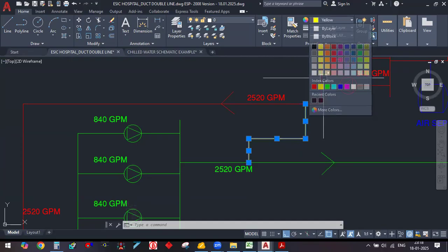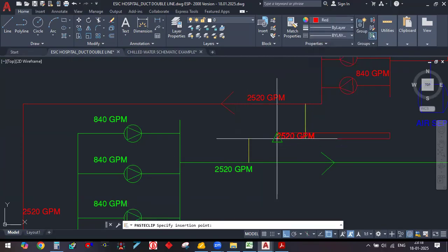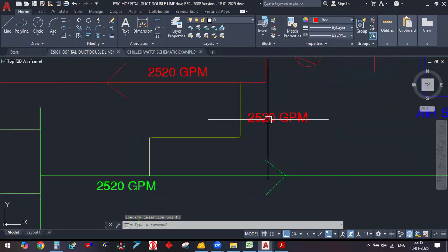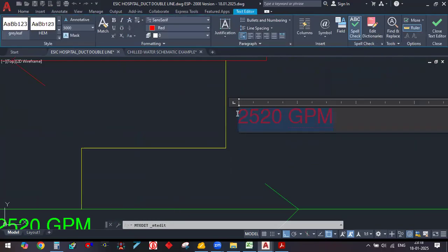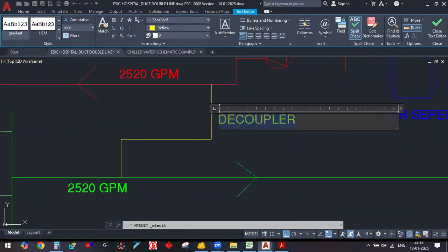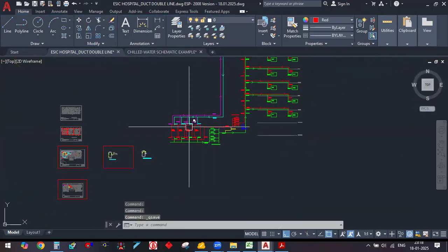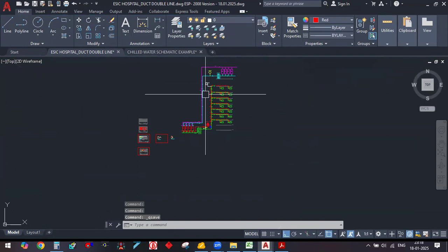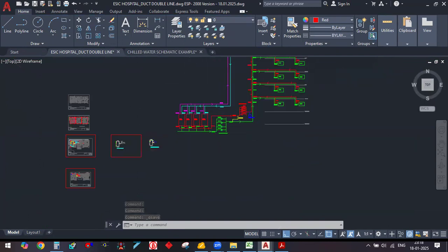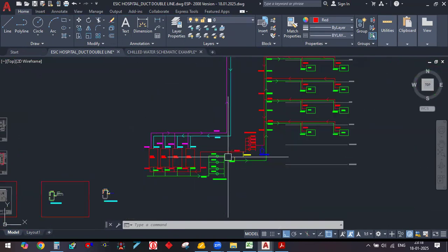Excuse me, sir. Now whatever we have done, this is the water cooled chiller. In the air cooled chiller, this cooling tower will not come. Yes, in the air cooled chiller, you just have to remove that. Rest everything remains the same. Instead of this cooling tower, from the chiller itself, you will have one supply line and one return line. See here, the same way it will be there.